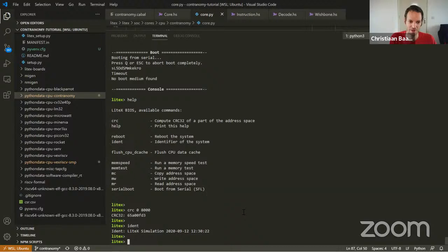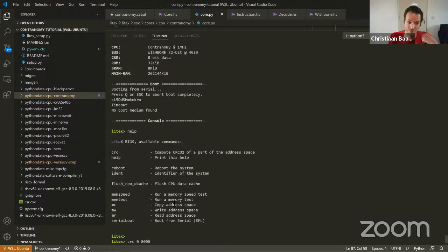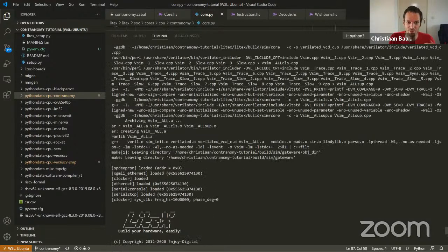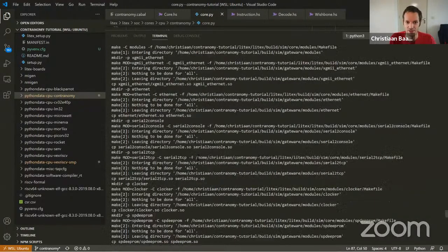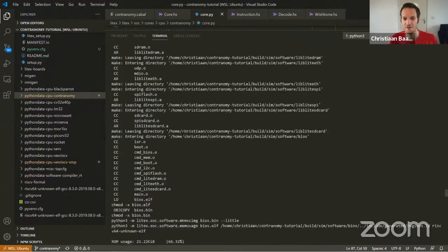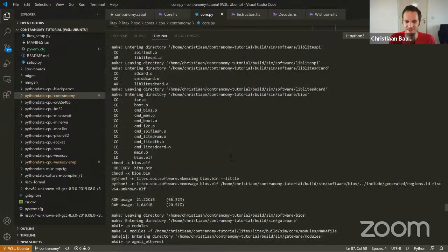And so you can play with this. You can make mistakes. If you go too far, you're going to go outside of the available memory. If we scroll up a bit, it's saying where stuff lives. So SRAM doesn't start until here. So if we access illegal locations, it is going to crash.